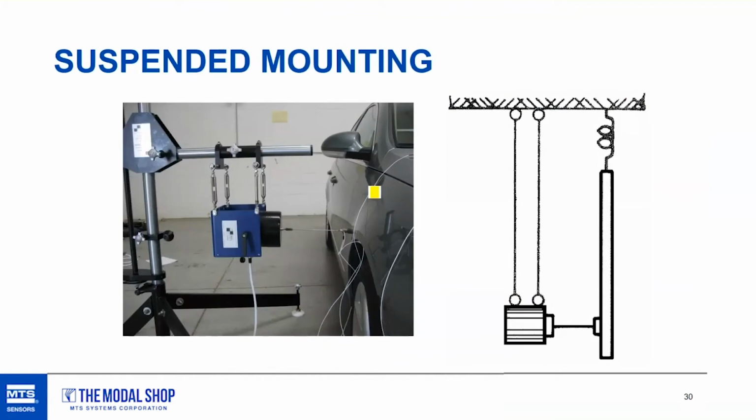A lot of times we like to add a little bit of weight to the shaker. We can apply some inertial blocks to the bottom of the trunnion base on the shaker, so you get a little bit more oomph when you are pushing against the structure, especially if you're doing some very low frequency excitation, where typically you get a little bit more displacement on the settings.